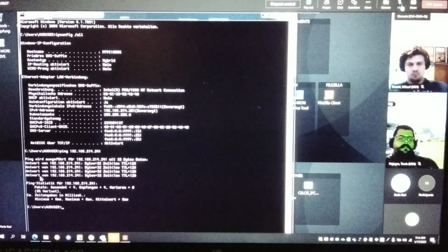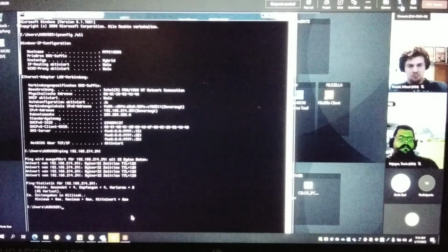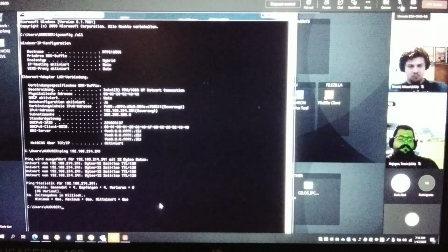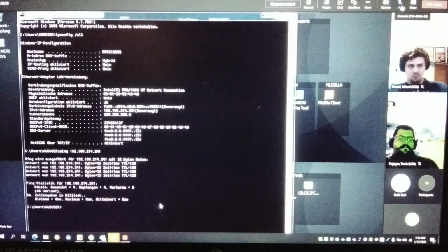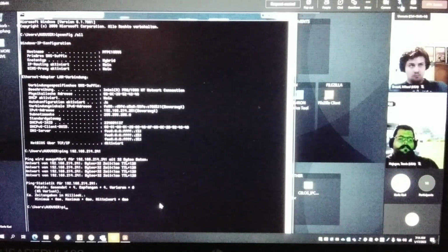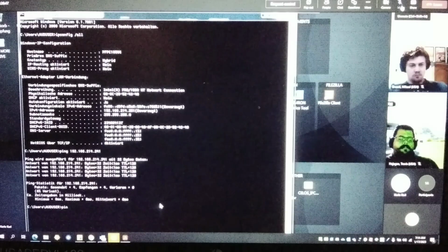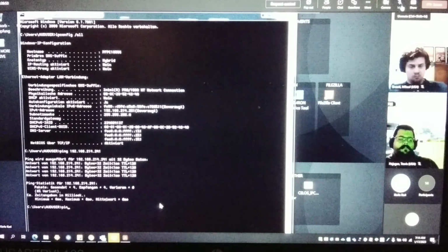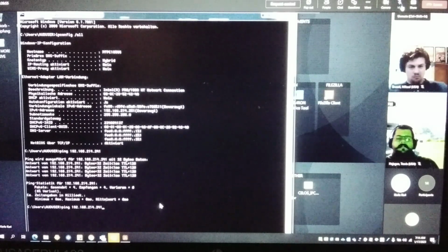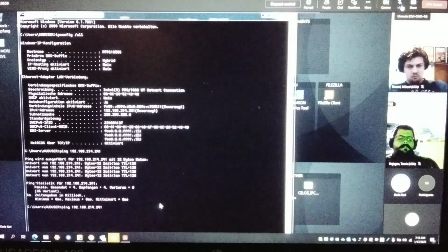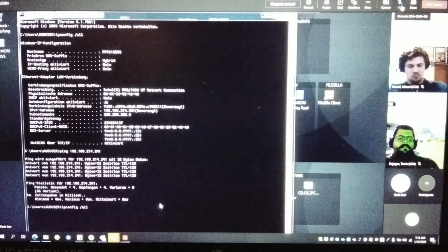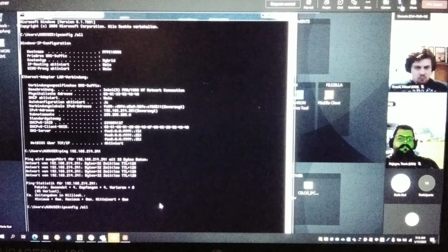What will happen if I start the command a second time? And also here I can tell you a short trick. If you press the right arrow button on your keyboard, you can recall the last command bit by bit. If you press the vertical, the upright cursor control button, the complete command will occur. And when I press the button a second time, the command I used before will again be visible in the input line. Okay?